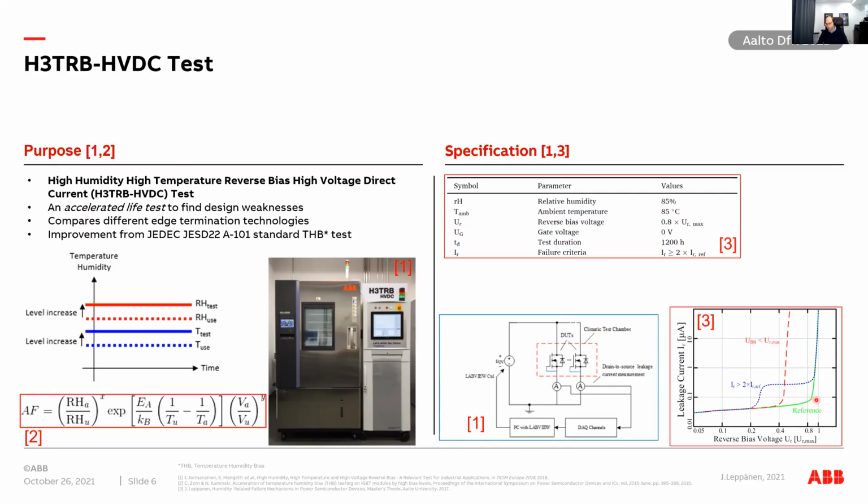And then at this 1 or close to it, we will have a breakdown. And then the leakage current increases dramatically. And this is the region where we don't want to be. Of course, it will fail if we were very close to this in normal operation. So that's why we use this 80% typically.